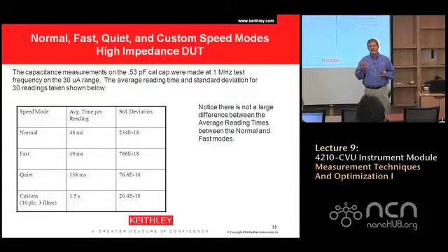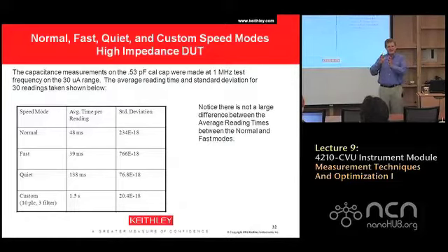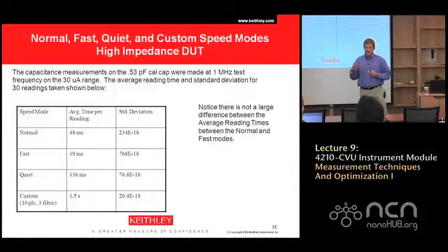We just keep sending it in, the noise keeps going down. So we don't have the concept of averaging mode in here. If you look at the way our menus are structured, they still look like that, because everybody's used to using averaging or power line cycles to reduce noise. But the truth is, this is a continuous aperture instrument. The longer we feed the AC signal in, the more the noise goes down, at least until we hit 1/f noise.